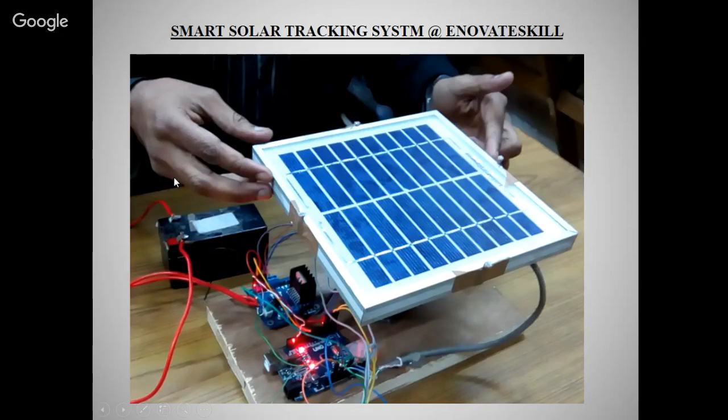This is the battery I have used, a 12 volt battery. Here you can use the battery or an adapter for power purposes. And this is the motor driver IC I have used, the L298 motor driver IC, or you can also use the L293 motor driver IC. This is the Arduino microcontroller board.